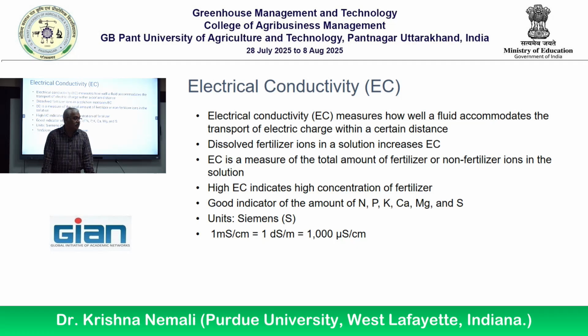Yes. We add a tiny bit of micronutrients, so their ion concentration is so less. These are the most dominant ions. So EC is a good measure of macronutrients. If you are really into micronutrients and you want to measure those concentrations, you may not be using this EC measurement. You probably have to use something else.